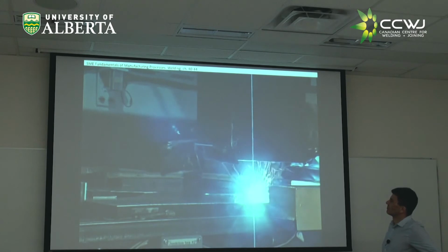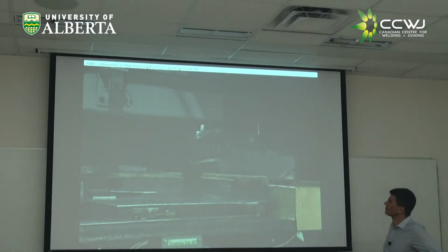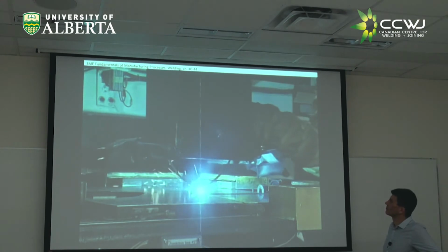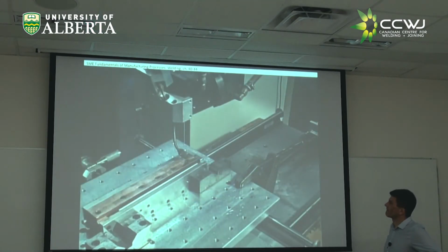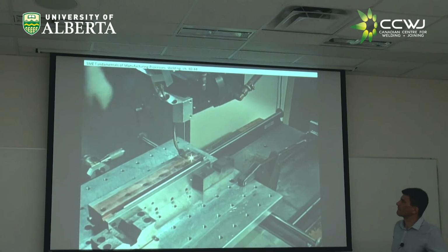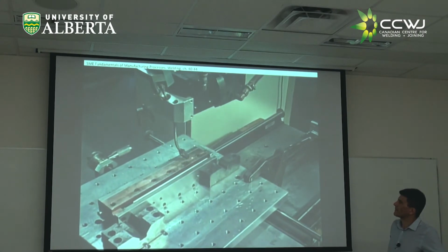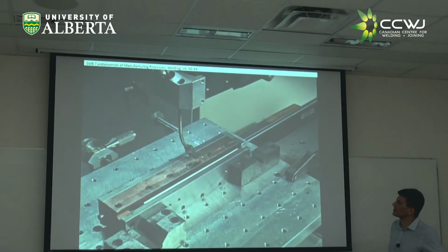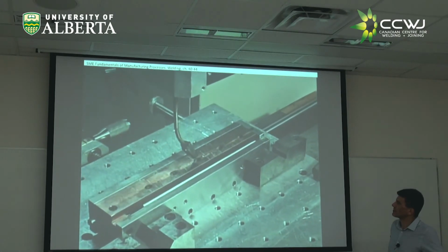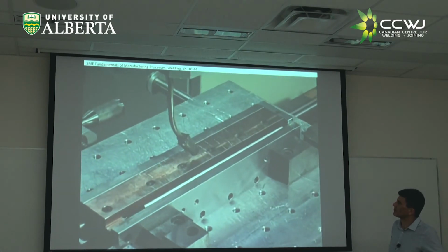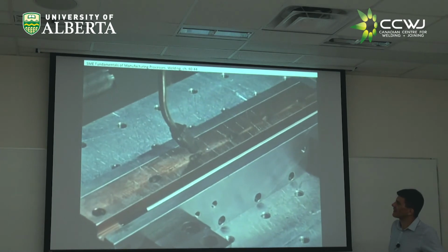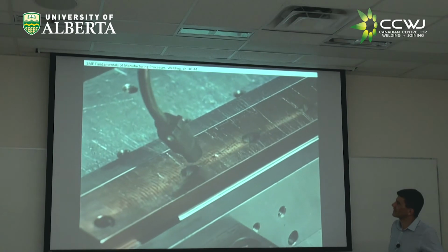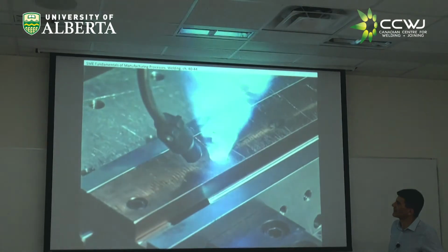Inert shielding gases are normally employed, usually argon, helium, or a mixture of the two. Welding speeds are usually much higher than other welding processes, thus limiting heat-affected zone size and workpiece distortion. In addition, because of the intense, precisely focused heat, welds can be quite deep. Also, welds can be made in confined regions and between dissimilar metals.